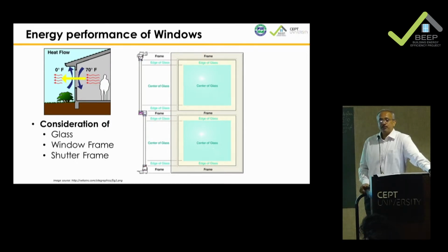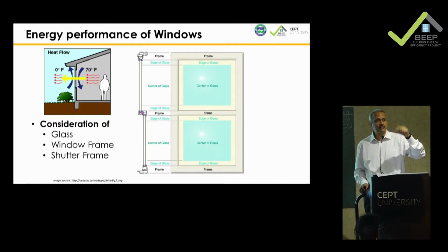Now things become more complex, because thermal bridging and thermal breaks become more prominent when it comes to glass, or windows rather, sorry. In walls, it is pretty okay: if you have 5 square meters of wall, or 10 square meters of wall, at the most your mortar or cement does not have very different conductivity than your brick. Yeah? It's not like insulation and an aluminum screw. There is huge variation in conductivity between insulation and screw, not as much as between a brick and mortar.